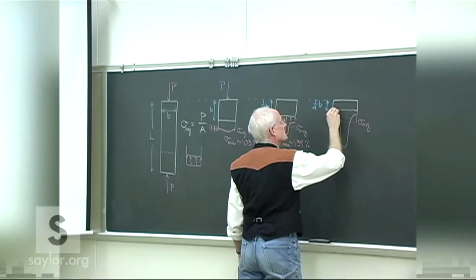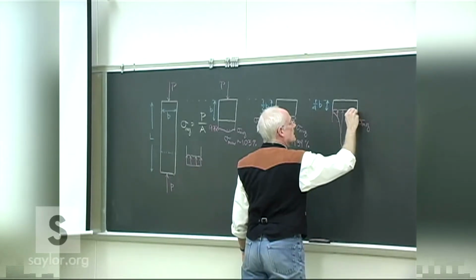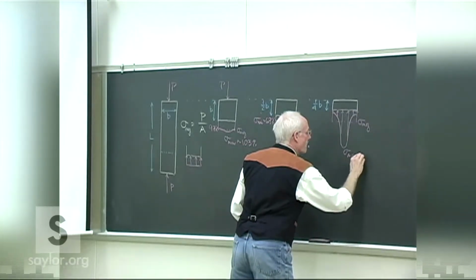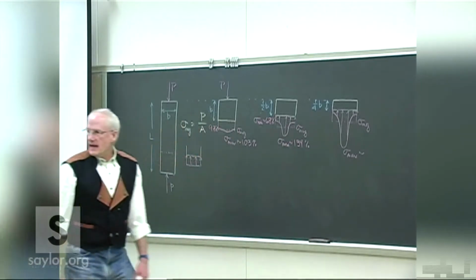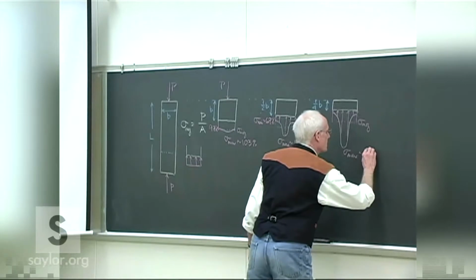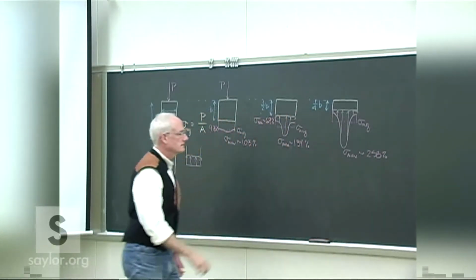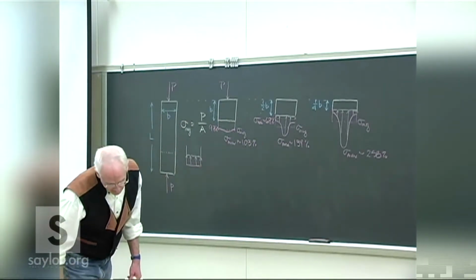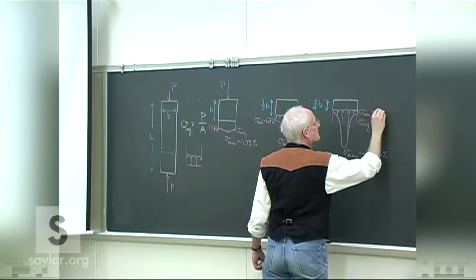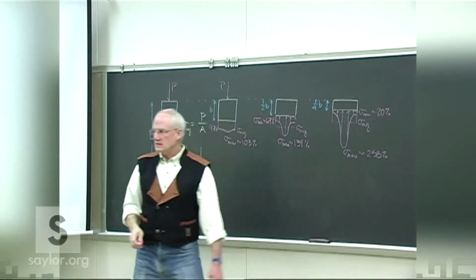The actual stress distribution is much more something like that now. That maximum is at about 258% of the average we've been using. The minimum at about 20%. Now that's not the concern, because we don't design for the minimum, we design for the maximum.